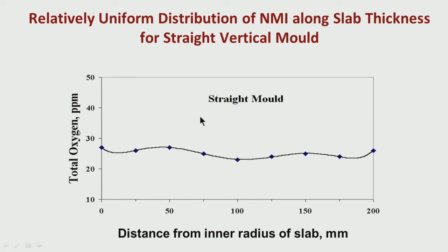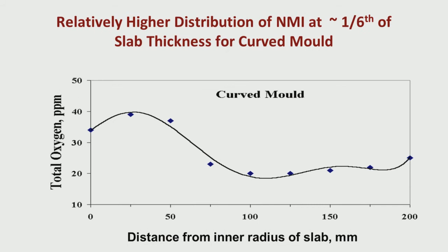So, if you have a good inspection facility, then you can find out at what stage these defects are coming out and what the distribution of the defects is, like whether defects are coming more on one surface or near both the surfaces. If you roll a slab, we will find that defects are coming more on the surface which corresponds to the inner radius of the caster.